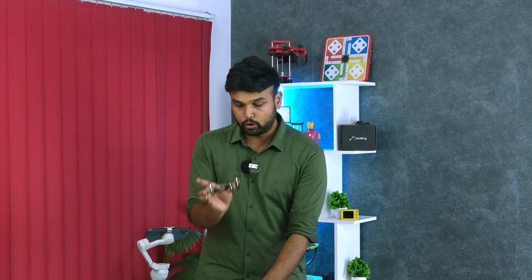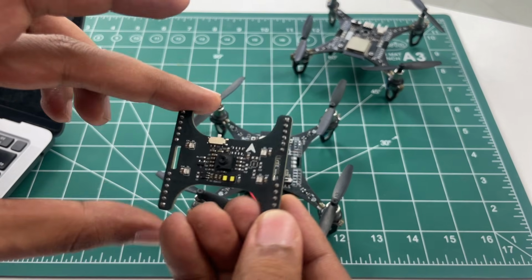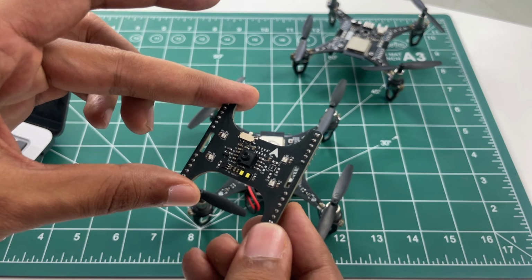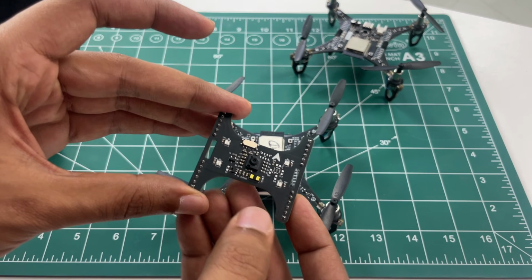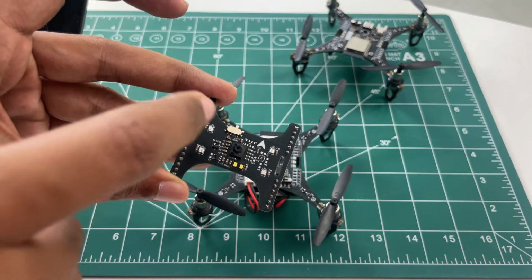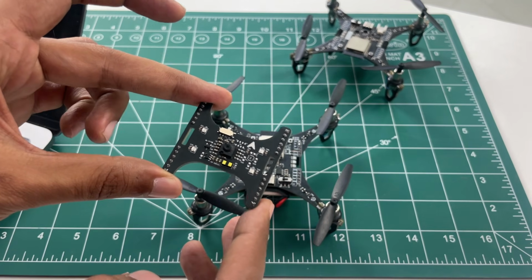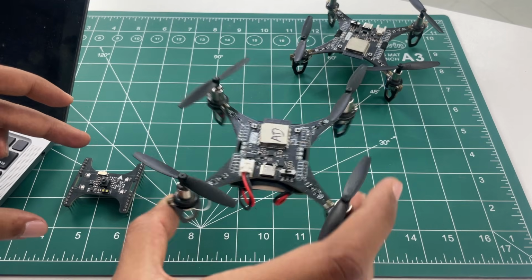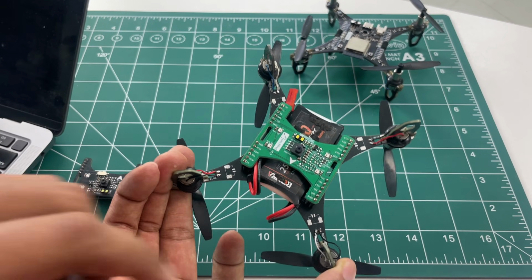Also, in this tutorial, like I mentioned earlier, we're going to make this drone fly on its own, meaning it has to maintain its height and its position on its own. And in order to do that, you will be needing this flight positioning module, which you can see here. This flight positioning module enables two features on Lightwing. One is the ability to hold its height, called height hold, and the other is its ability to hold its position, called position hold. As you can see, there is a TOF sensor for height hold and an optical flow sensor for position hold. The drone that we are going to use for this demo will be using such a drone positioning module.